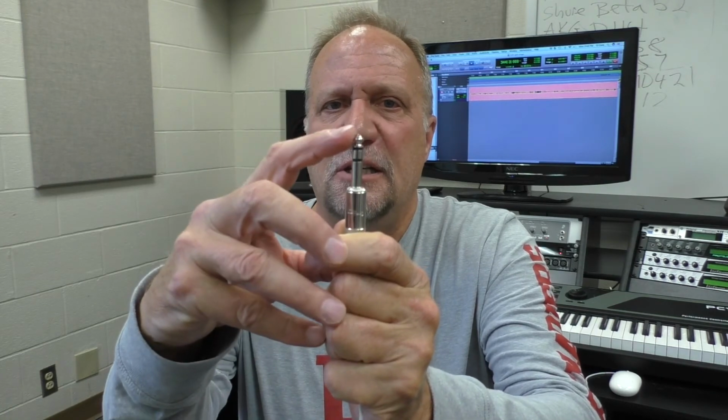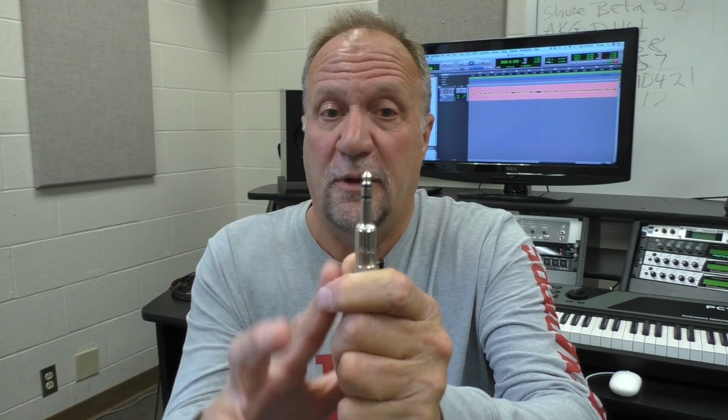The type of connector that can be used for a balanced signal is either an XLR type connector, which, if you look closely at it, has 3 different pins in it, or a tip ring sleeve, which uses a tip, a ring, and a sleeve, so that's got 3 different conductors on it. So these are the 2 most common types of connectors being used for a balanced connection. For an unbalanced connection, they use primarily what's called a 1/4 inch phone plug that just has the tip and the sleeve, so it has a signal and a ground.